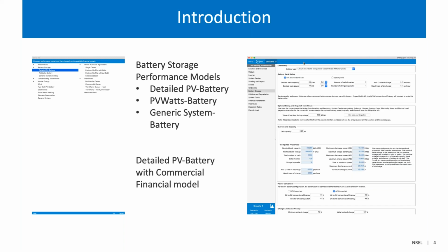Similar to how the full PV model allows for detailed modeling of the components and system design, the full battery model allows for selection of different chemistries, electrical and thermal behavior, efficiency losses, and lifetime degradation. Also, there is much more flexibility in the dispatch modes. The PV and battery system can be AC or DC connected, where they share a hybrid inverter characterized by the selection on the inverter page.